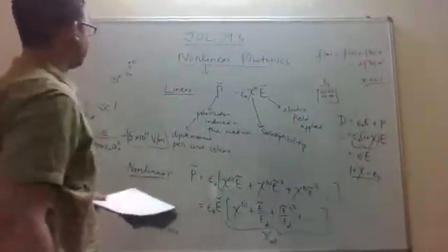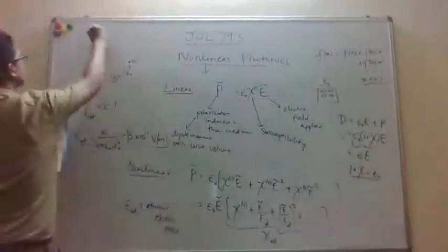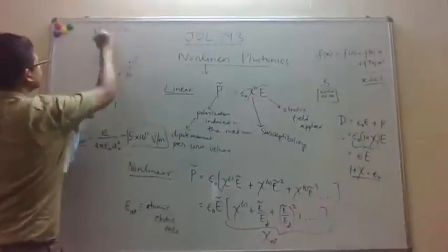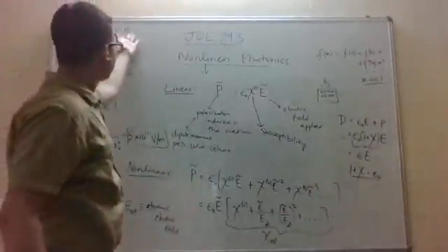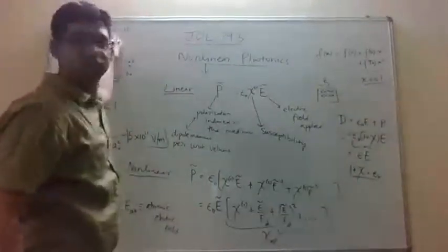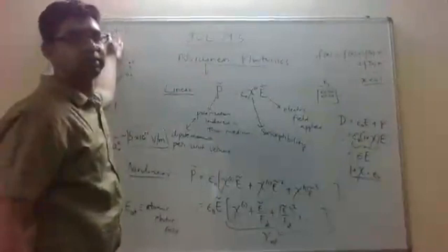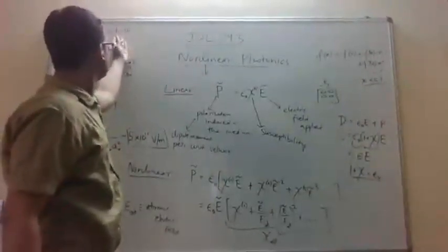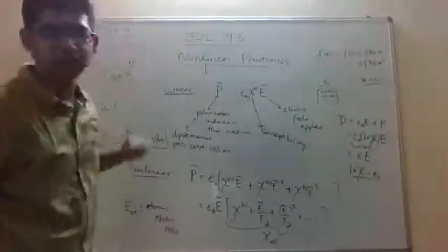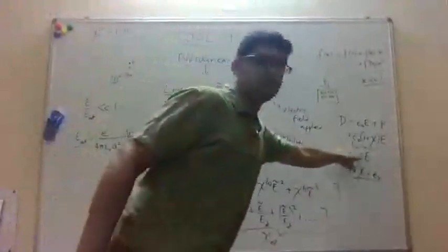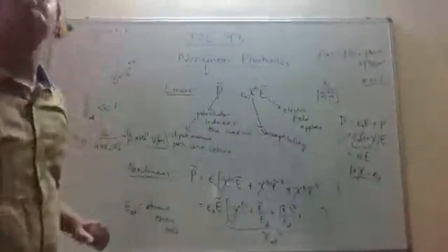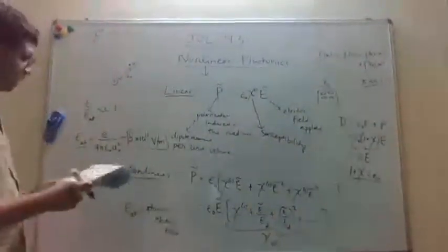Right? So then these nonlinear susceptibility typical values. So the linear susceptibility typically varies in the range from unity to 10, right? So free space or air has susceptibility 1, right? And most dielectric materials have susceptibilities in this range 1 to 10. And 1 plus susceptibility is basically the dielectric constant. So that basically gives you the range of the dielectric constant of most materials, right?